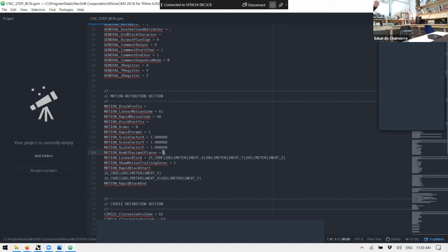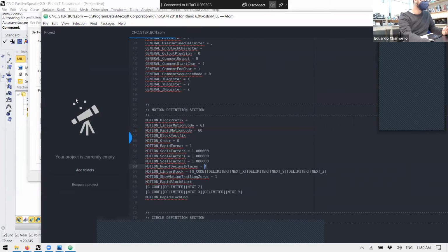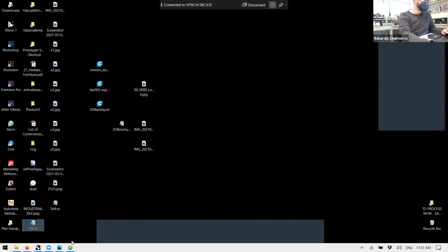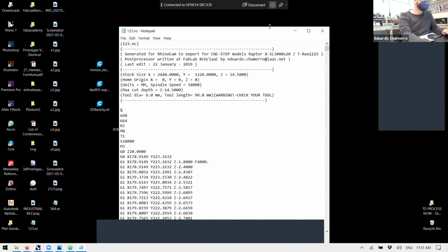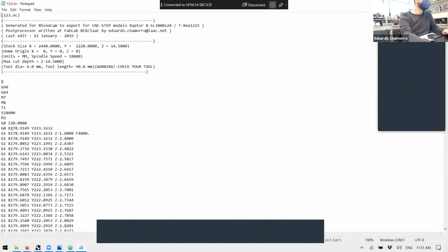Some machines don't like 4 digits. Some machines like only 2 digits, and if you have 4 digits, they don't read the G-code. Some machines don't like the G-code formatted like that, as an assembly. They like it with spaces between the Y and the number. Some machines don't. When I say machine, I mean the firmware that runs the machine, so it's actually how the base code of the machine is built. Some machines also like the G-code just in a row without the spaces.